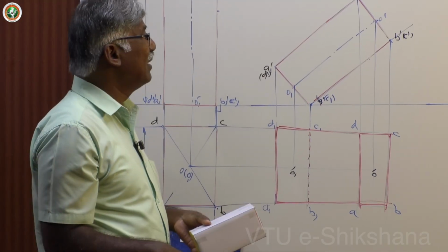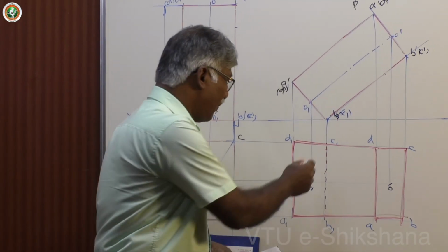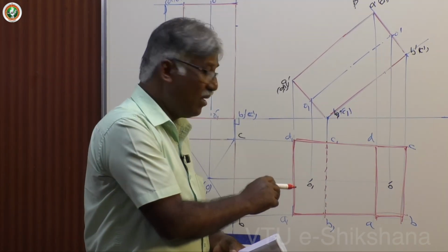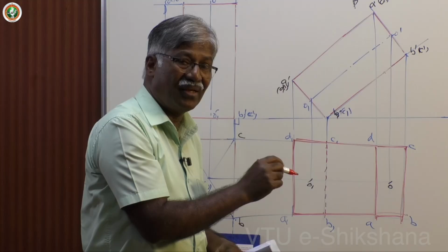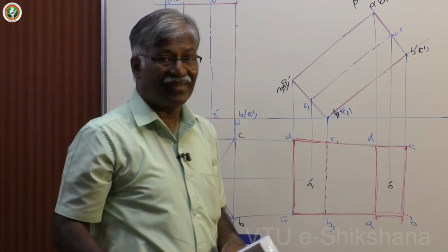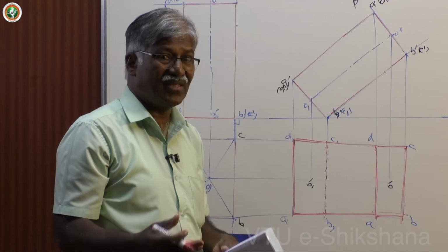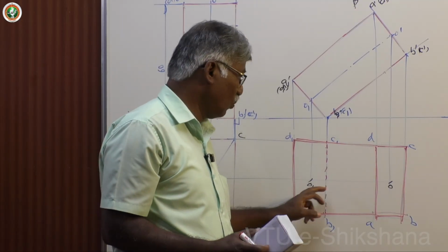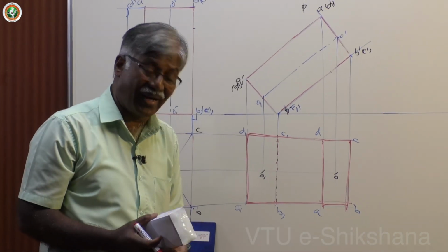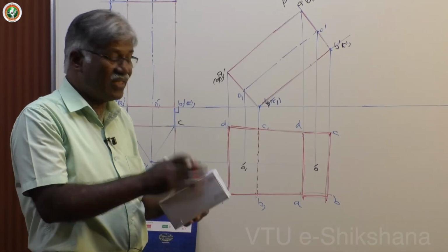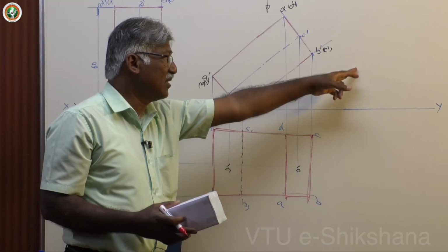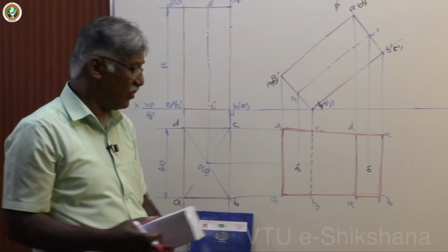Even in the farthest item method, the farthest item is C1, B1. Number of lines connecting to that are dotted, but all lines connecting to that are what? Boundary lines, except this. This is actually the top face. Like this you have to analyze. So, either you can mix the concept, otherwise you try to keep the key surface concept to do this. There is little confusion with the square and rectangle because these surfaces coincide each other. So, in this problem you will get clear idea. Okay, that is in finalizing the final front view you get clear idea.